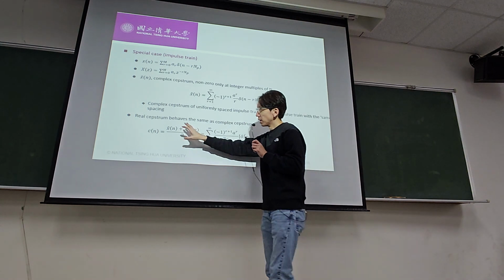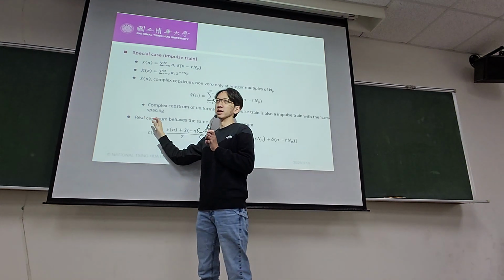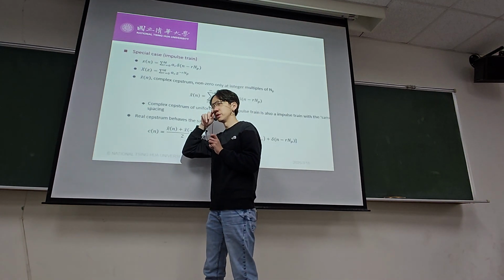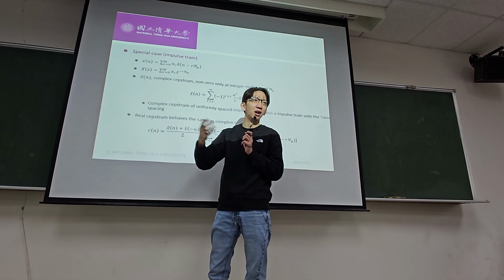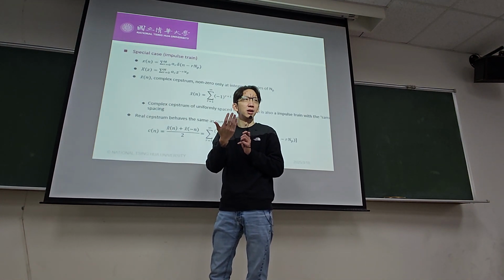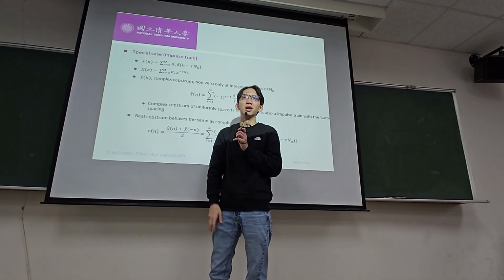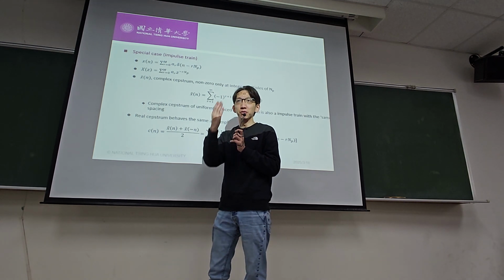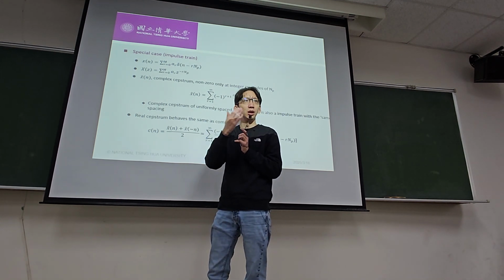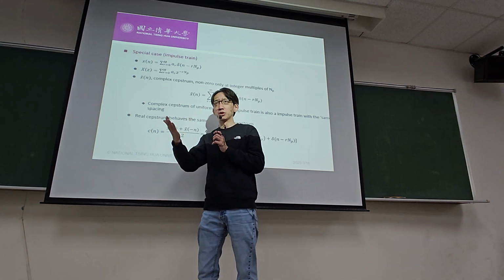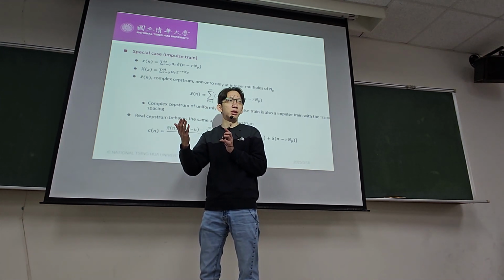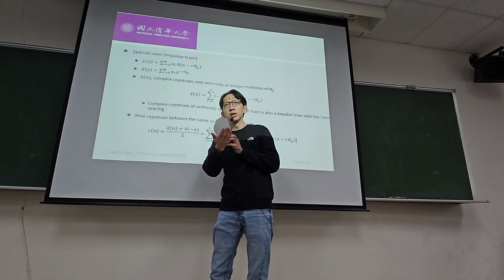So instead of thinking about this cepstrum as some special math domain, think of it as just another time-domain kind of thing, but you have stuck a log into the frequency domain before you do the inverse. That's all it's doing. Z transform, stick a log, do an inverse, and you're back to the original discrete time index.